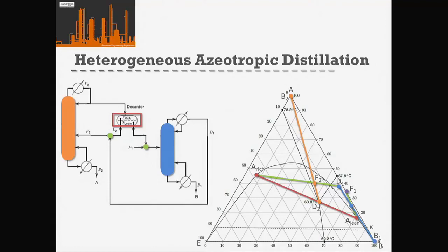But fortunately, it's possible. Okay? And we can now see the specified ratio point for F2. Okay? So what we managed to do is just using the same techniques all the way through of knowing that the distillate and the bottoms are on the same residue curve, and the distillate, the feed, and the bottoms all lie on the same straight line, we've managed to essentially start to increase the complexity of the systems that we're drawing